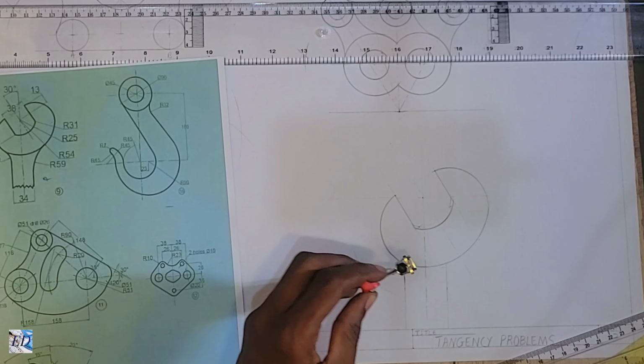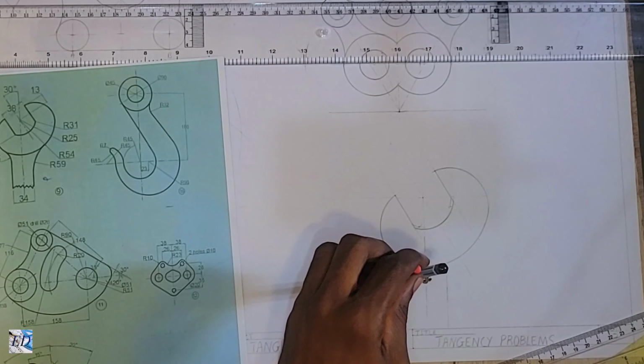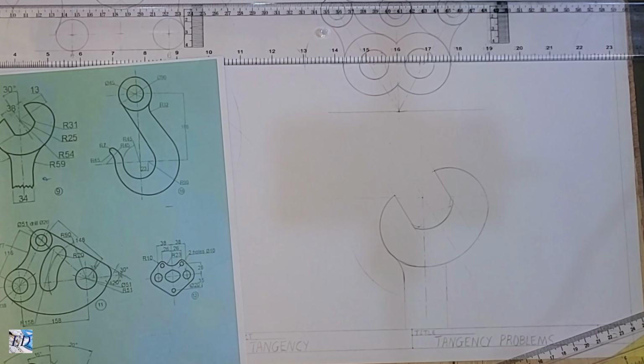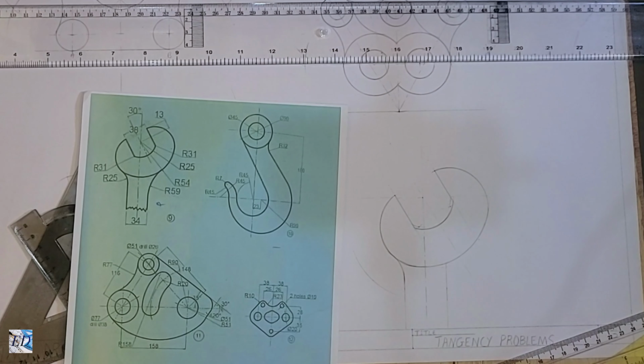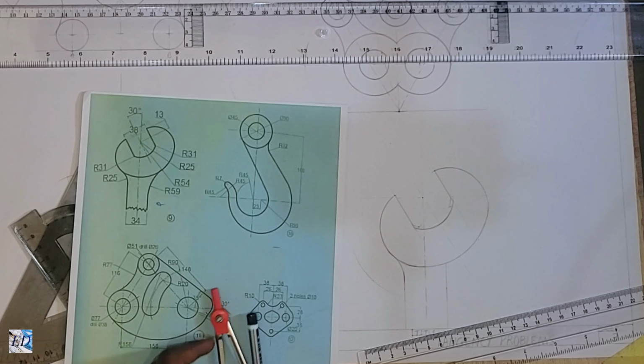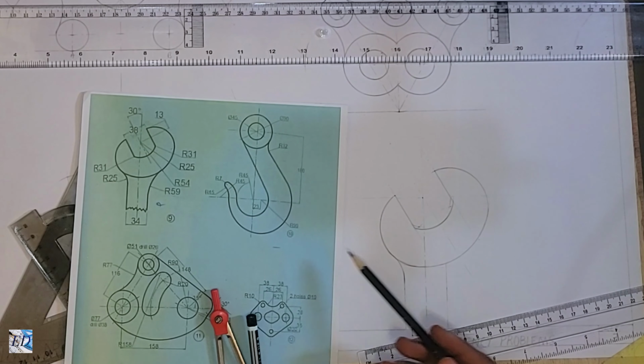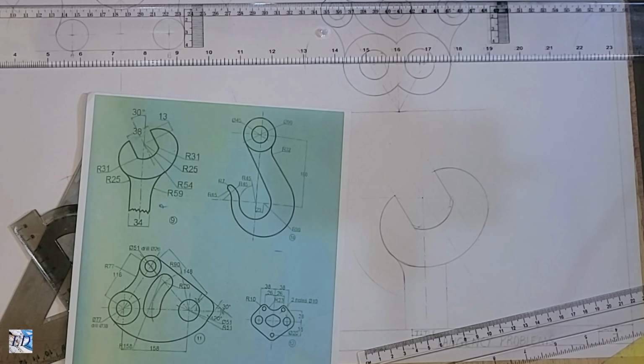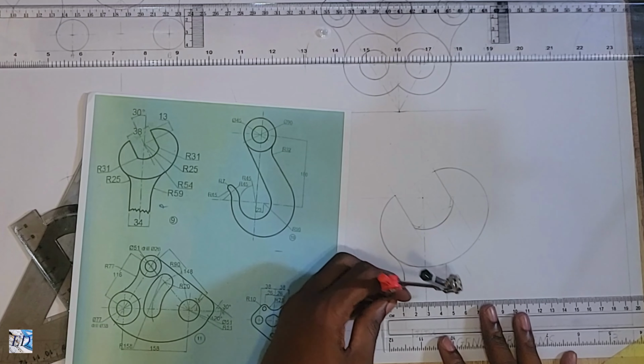Let's say drawing a test or something, or sometimes you're not even sure how to work around locating the second arc. You can use this approach. So we'll do the same thing for the other side, just so you see it being used one more time. Let's locate the distance where the center would be by adding 59 and then 54, because then it touches the 54 arc here. 59 plus 54 is 113, right? 113.